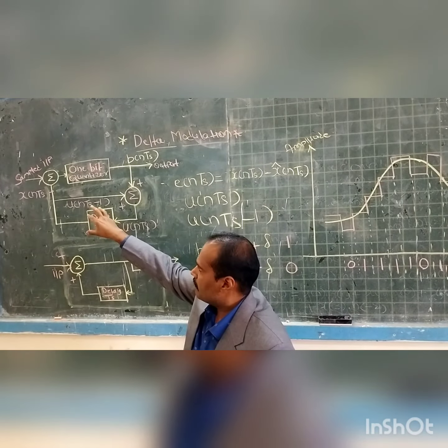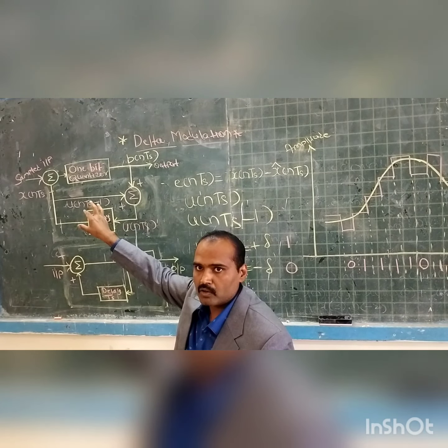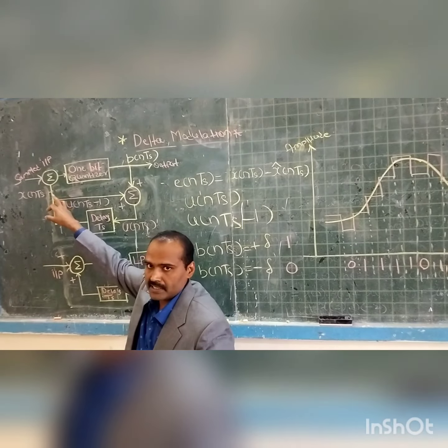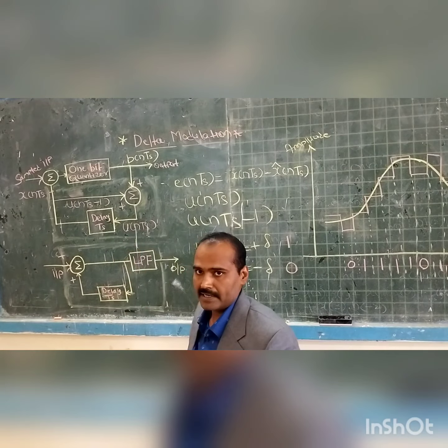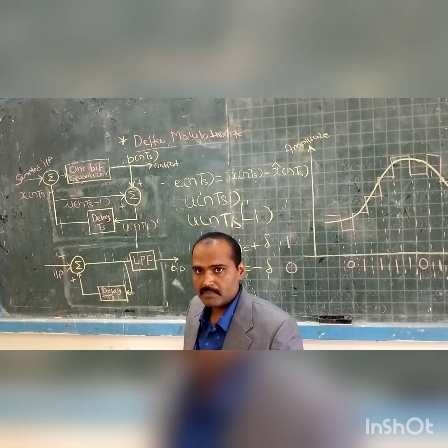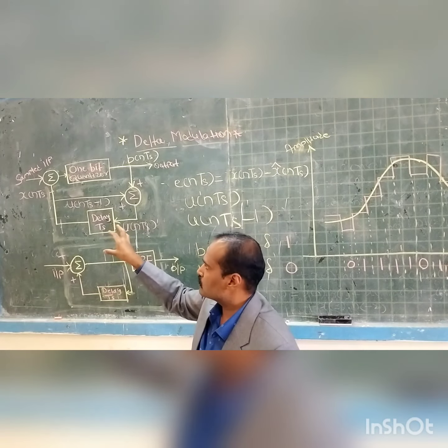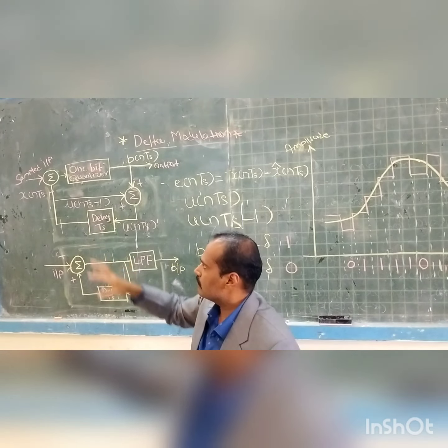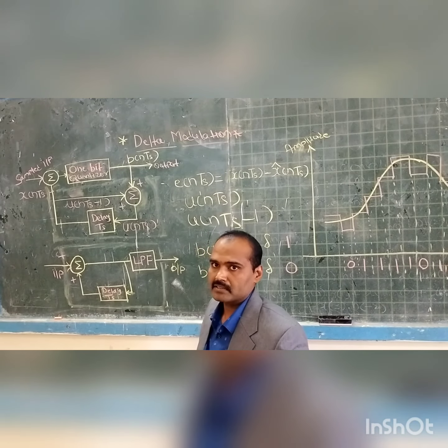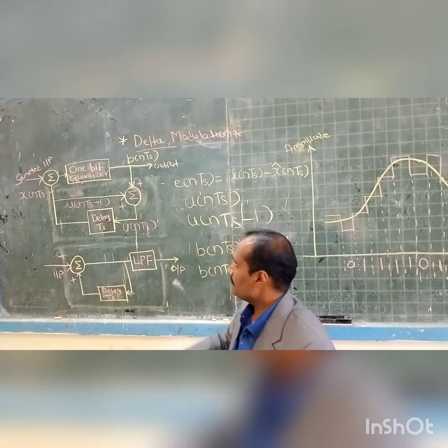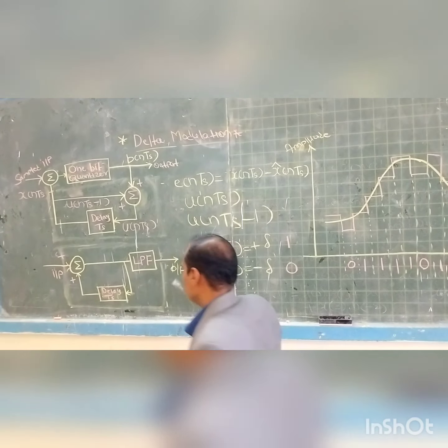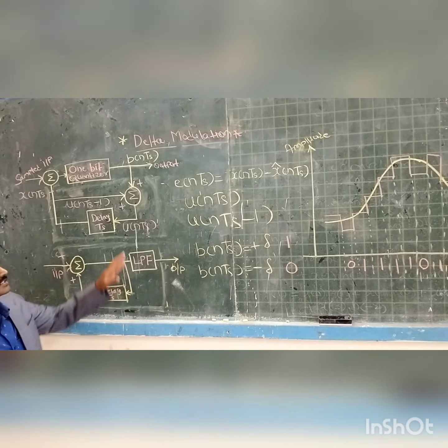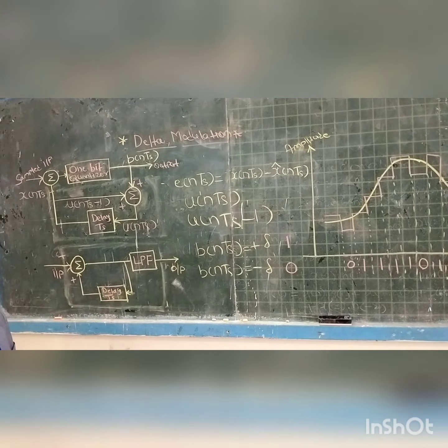First of all, we have one signal adder, or we can also say a subtractor here. So here we have one signal adder, and here also we have this signal adder. So there are two mathematical adders in this delta modulator. One of the inputs of this adder is nothing but the sampled input x of nTs. At the same time, with the help of these mathematical statements, we can clearly understand the working of this delta modulator.